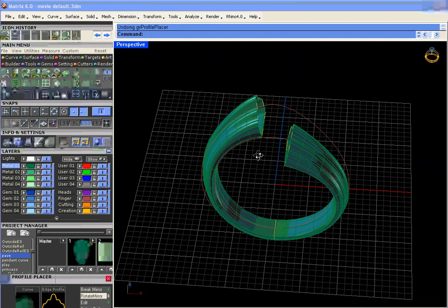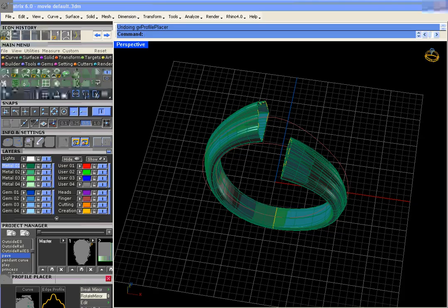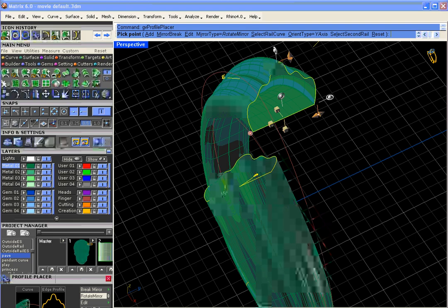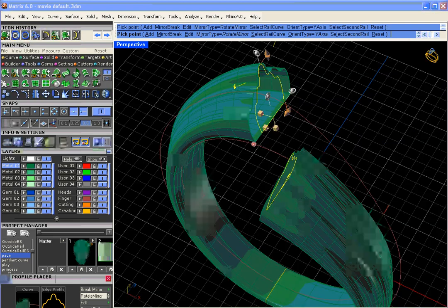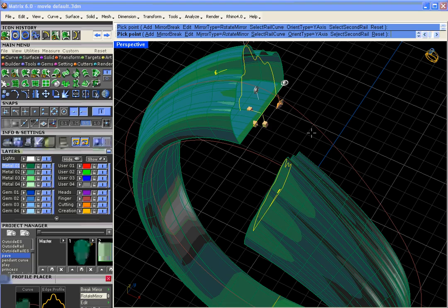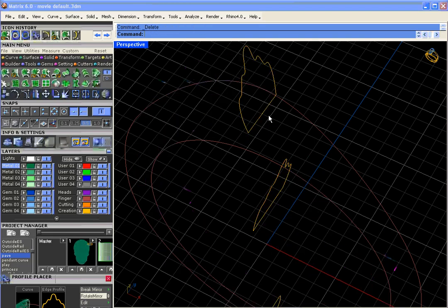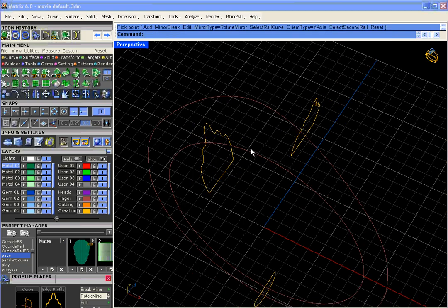So typically what I do if I want to do that kind of bypass look, let's come in here and go F6 MSR. We'll make this a little skinnier. Enter. And what I'm going to do is I'm going to re-sweep these. And I would just do it individually.